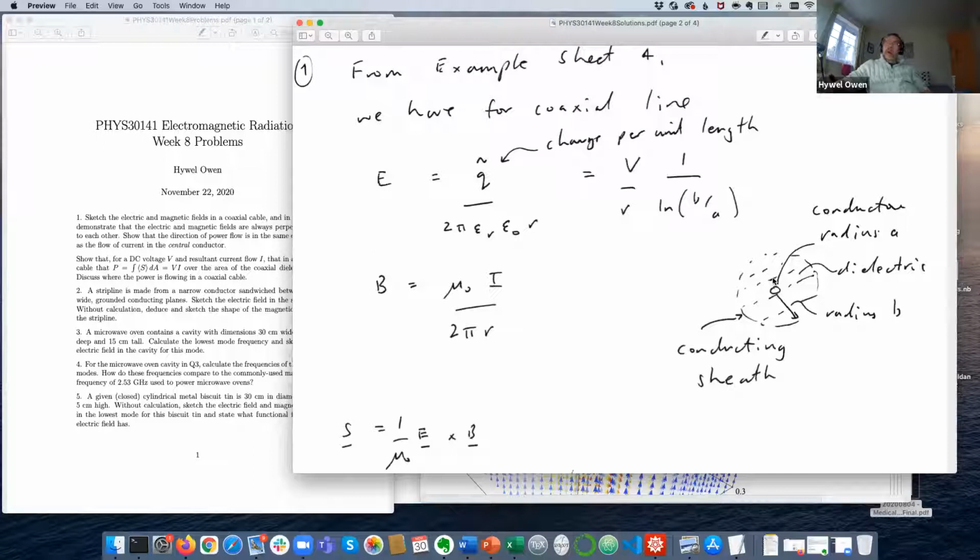And we can imagine, in a more general sense, if I had just two wires, like what are commonly called a twisted pair, so like many mains cables, the sheath, the current flowing in the opposite direction, may not lie concentrically around this conductor. It may lie all to one side, in which case there would be an electric field that passes from one to the other conductor.